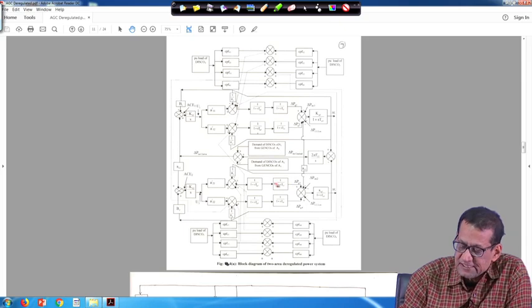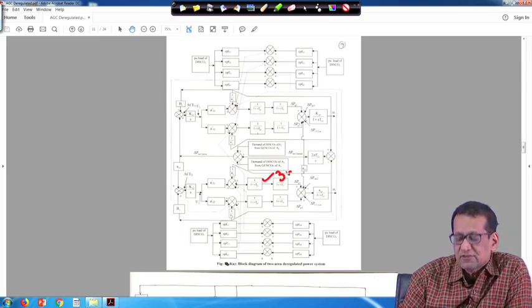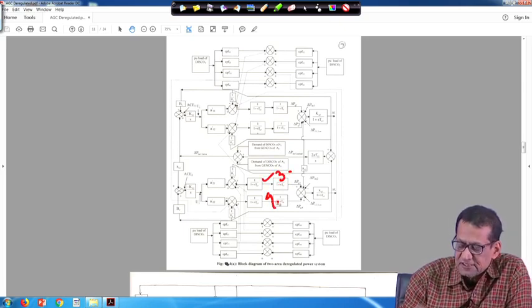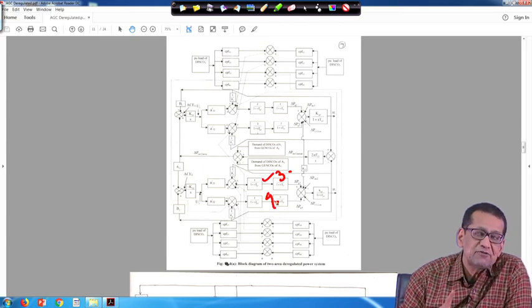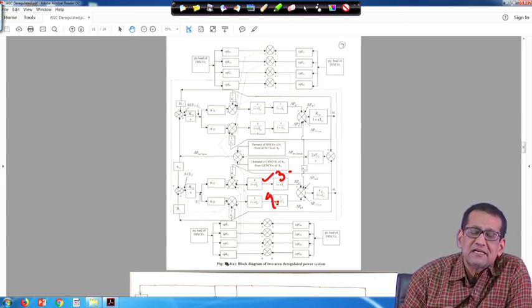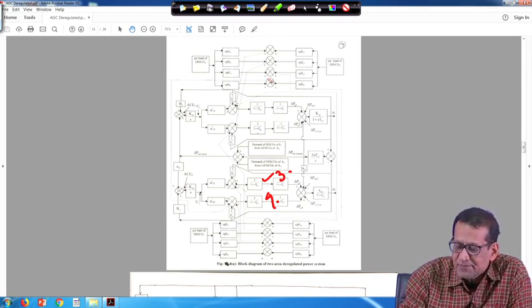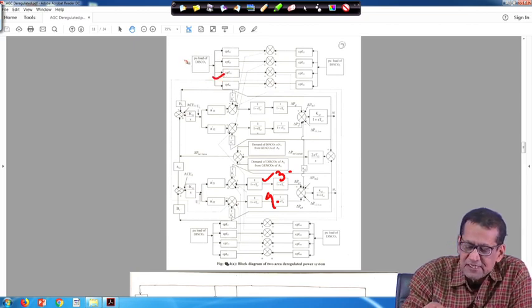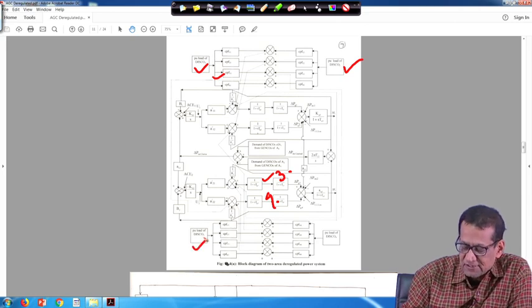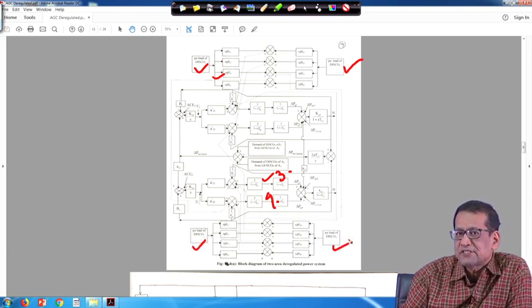So, this is your unit 3 for area 2, and this is GENCO 3 and this is your GENCO 4. When it is coming to your GENCO 3, then your delta P3 will be CPF31 delta PL1 plus CPF32 delta PL2. If you look into this, DISCO 1 has demand delta PL1, DISCO 2 delta PL2, DISCO 3 delta PL3 and DISCO 4 delta PL4. This we have seen, I have already just mentioned like this.